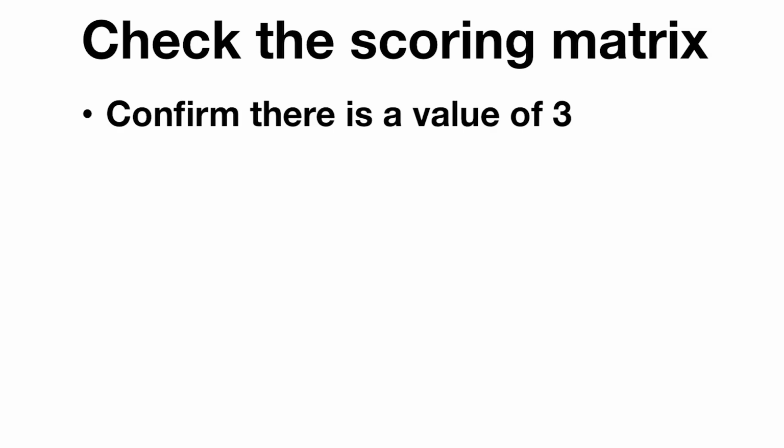Before moving on, you want to look at the numbers in your scoring pugh matrix. You want to confirm that there is a value of 3 in each of the design criteria that's serving as a standard.